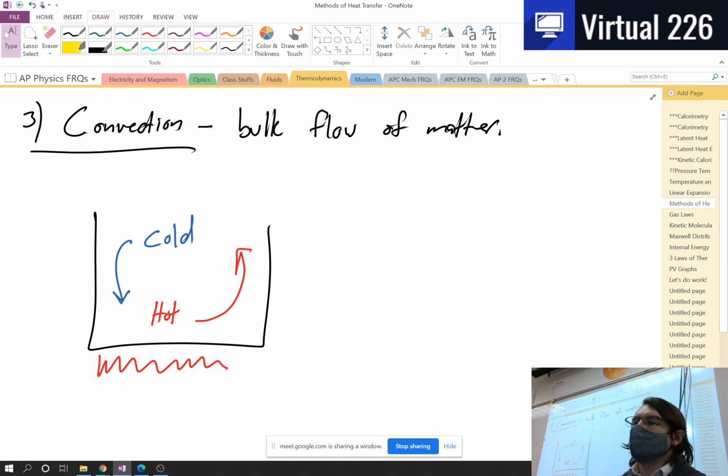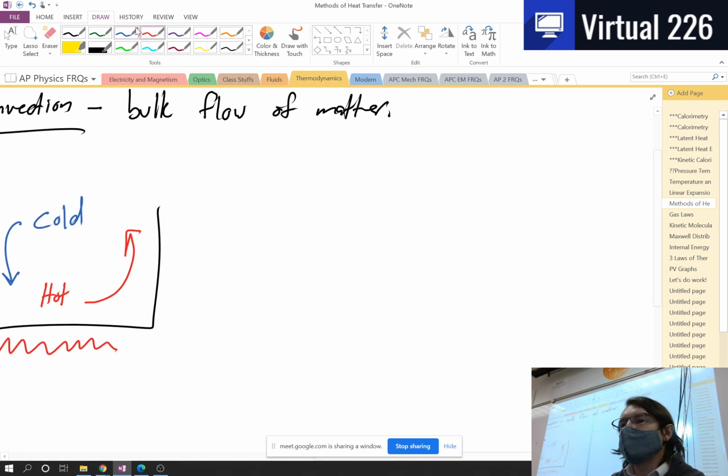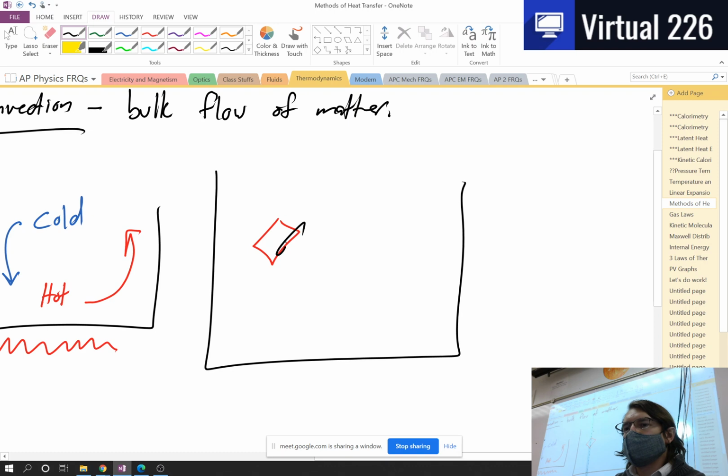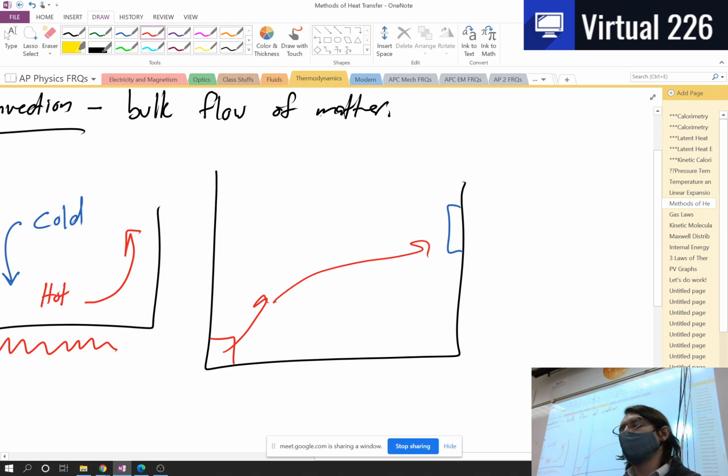In our homes, what we tend to do is you'll have some register vents on your walls or in your floor. So this is like a large room. We'll tend to put register vents in these rooms. And then we'll actually have return vents. And these return vents have two purposes. One is so that as the air comes into this room, it can convect out as we go through. And because this air is already slightly heated, your AC units have to do less work.